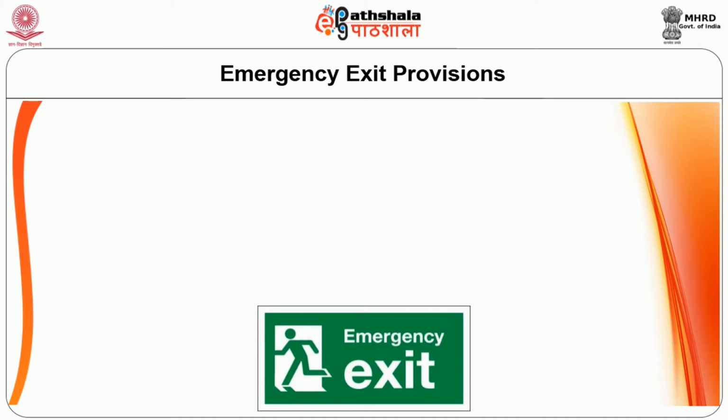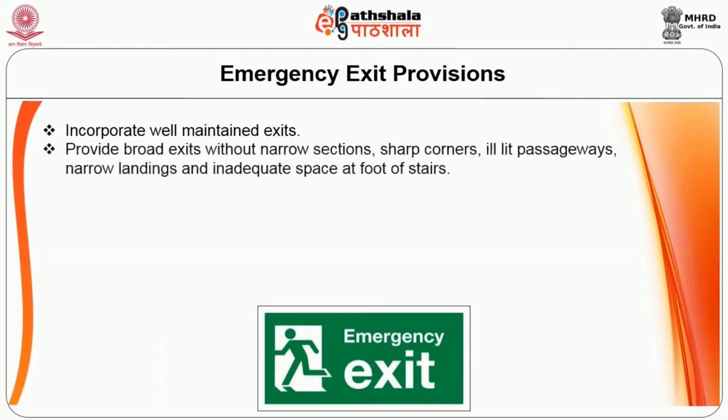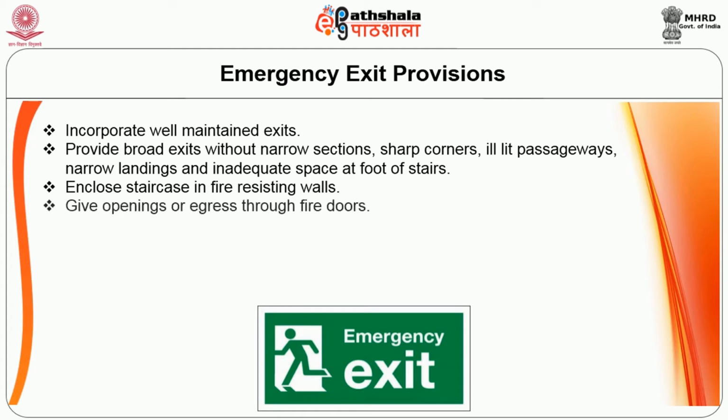Next, let us have a look at the hints for emergency exit provisions. Incorporate well-maintained exits. Provide broad exits without narrow sections, sharp corners, ill-lit gateways, narrow landings, and inadequate space at the foot of stairs. Enclose staircases in fire-resisting walls. Give openings or egress through fire doors.